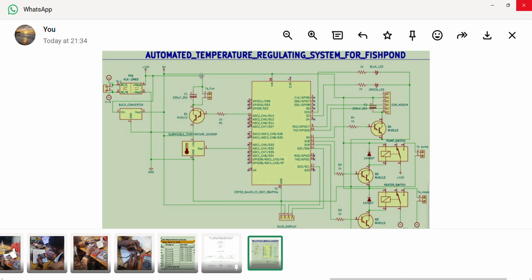And our control system is supplied by 5 volts. Now there are some components in the system which use 3 volts. For our system, it has that integration which converts the 5 to 3. There's no need of feeding them separately with 3 volts, it is created from here.